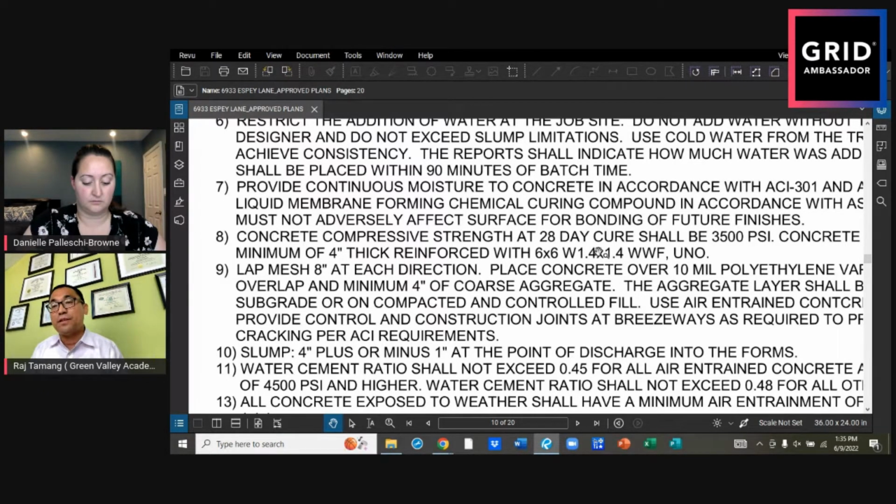The problem is people don't wait. You pour the concrete, next day you start doing the framing, which is not supposed to happen. But this is what happens. At least when you pour, after certain hours, it will get the majority of the strength. In 7 days, I think it gets almost 70, I have to check, but 70 or 75% of the strength.